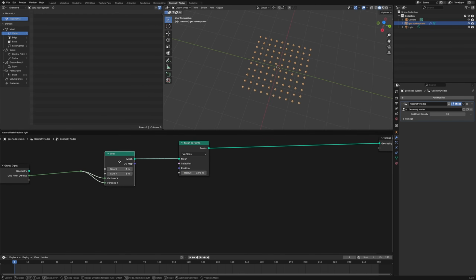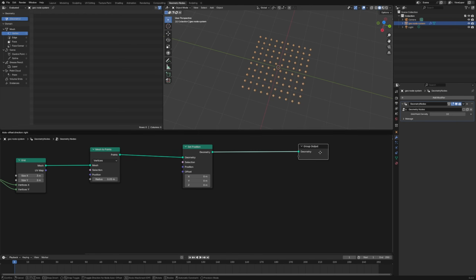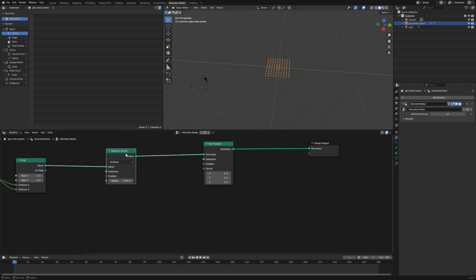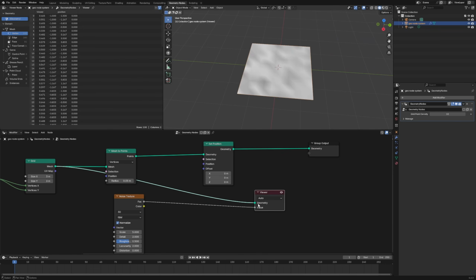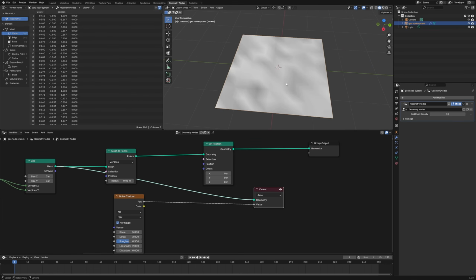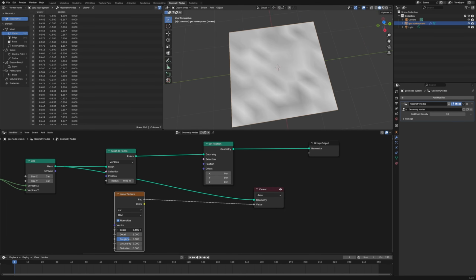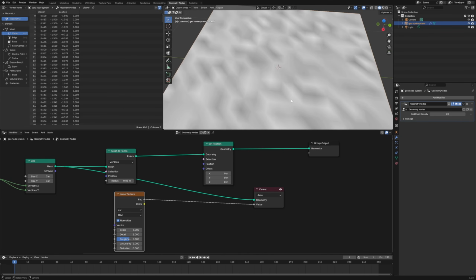The points are helpful because now we can move them around however we want. So we can do this, set position on these points. We can then have them go up and down or all sorts of things. One really easy thing to do is a noise texture. So a noise texture, let's preview this. So Control Shift, clicking the grid, and still holding Control Shift and clicking it, we're now going to have that value mapped on that geometry so we can preview it. So we see a noise texture. It's basically just a black and white value moving across all of this different mesh data. So if I make the densities bigger, we can then see it a bit more cleanly.